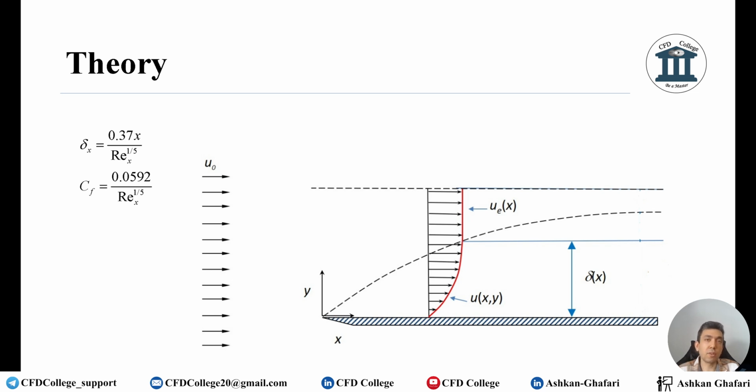So you should keep the y plus below 1 or below 5. Below 5 is fine, but if you can use a finer mesh, please keep it below 1.